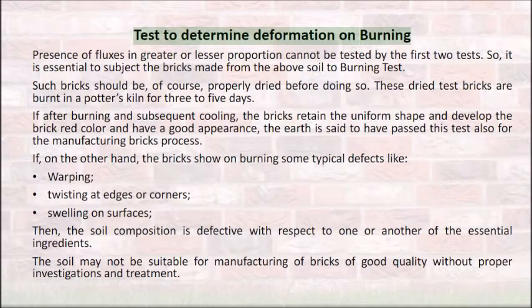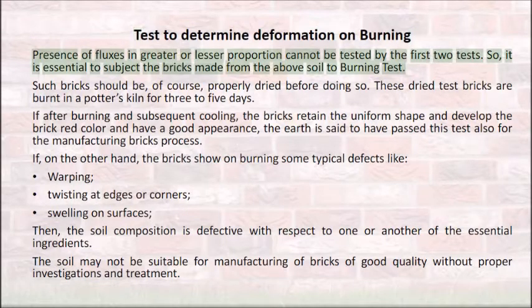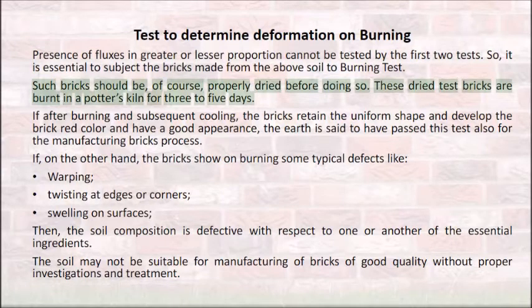Test to determine deformation on burning. Presence of fluxes in greater or lesser proportion cannot be tested by the first two tests. So, it is essential to subject the bricks made from the above soil to burning test. Such bricks should be, of course, properly dried before doing so. These dried test bricks are burnt in a potter's kiln for 3 to 5 days.